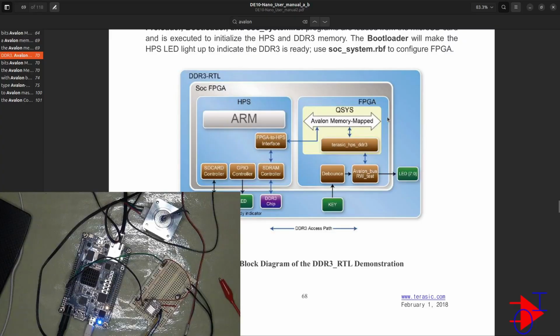The FPGA has access to the GPIO. It's going to control the motors. The HPS is going to pass on the position, speed, and direction to the FPGA. So essentially right now we want to control the speed of the motor. That's what we're doing in our baseline program. So from the C++ code in the HPS, we will just write out the 4-bit output to the FPGA. Now with that 4-bit output, we will take that in the FPGA and basically